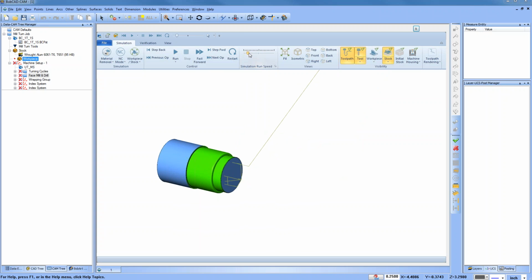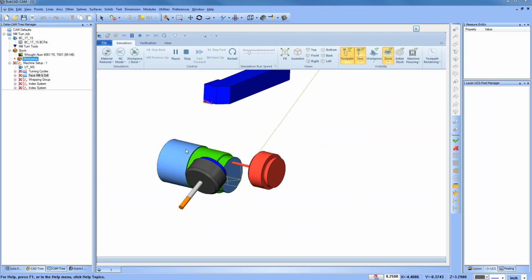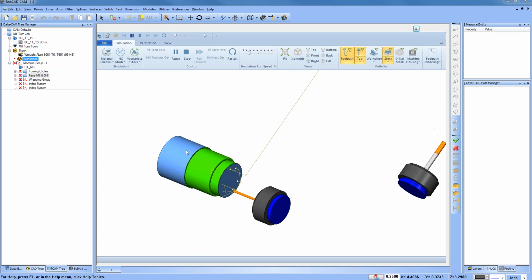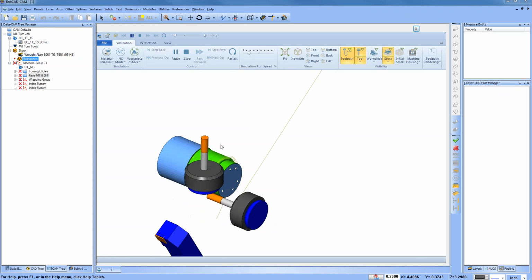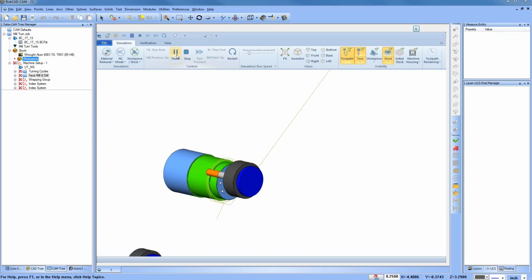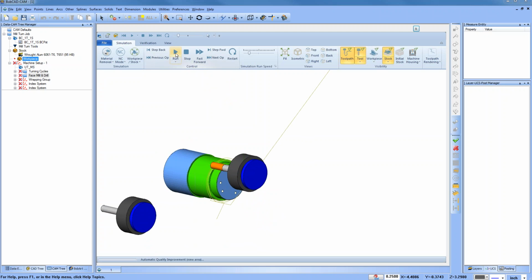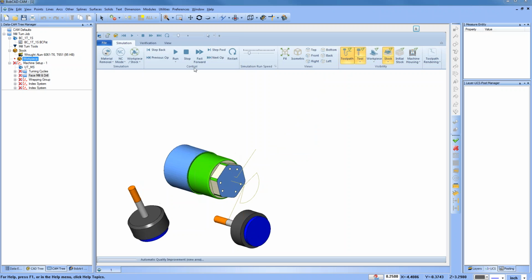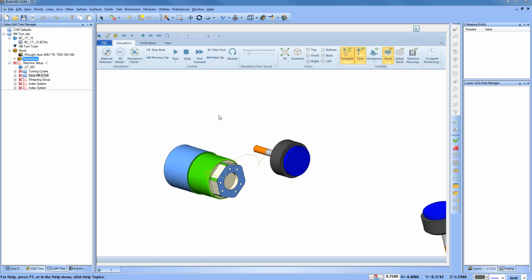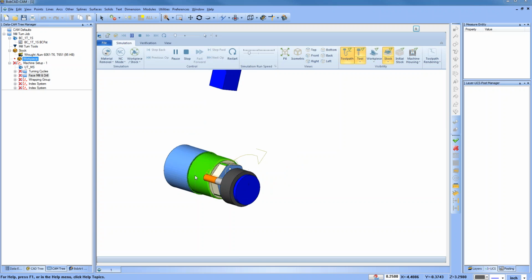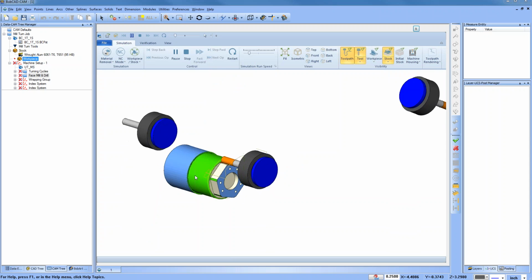From here, I'm going to just drill some holes on the face of the part. It is showing up red because my depth of the hole was deeper than what was modeled. The next thing that I have here is an open pocket, so I'm doing an open adaptive pocket on the face of the part. You could do a profile routine there as well, and I'm going to show both of them. This is probably a finish on the face of the part as well. So we drilled, oh no, I did a circular pocket. Now I'm doing a profile to finish the wall. I come back and break the edge.